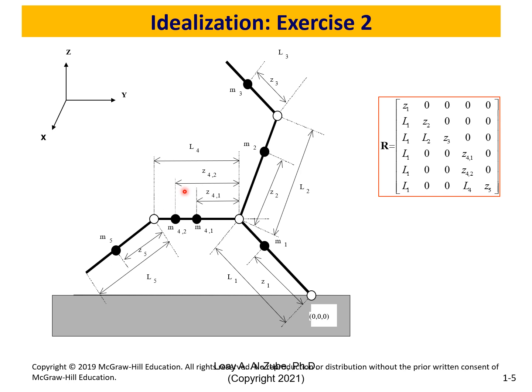So your upper extremities, none of them is connected to make a closed loop, right? You can't have this and make the subject move. It's impossible. So all segments should be free, no closed loops. Now, this is the first segment. I'm going to identify an origin as 0, 0, 0 point first, before I do anything. And then I will construct my relation matrix from that point.